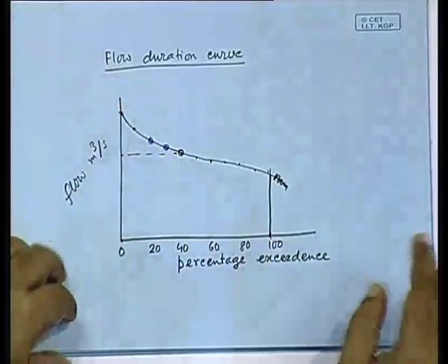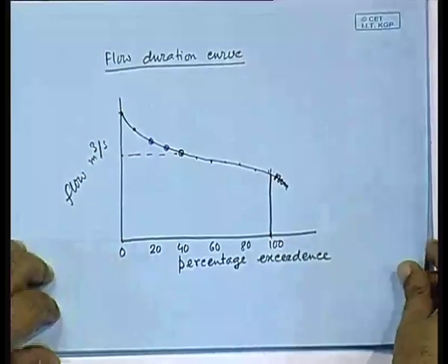Okay. So, if it is designed for a particular head, say 50 meters, and now the head is 52 meters, then that will cause a difference in the flow. So, what you have drawn, that the capacity of the flow is this much, it will be slightly less. So, how much less?